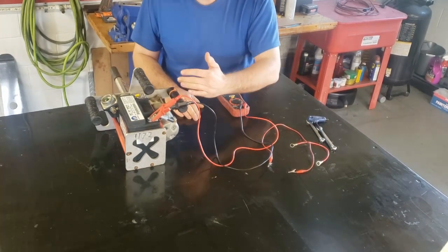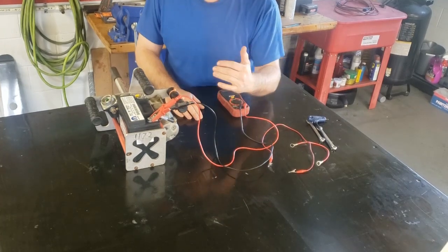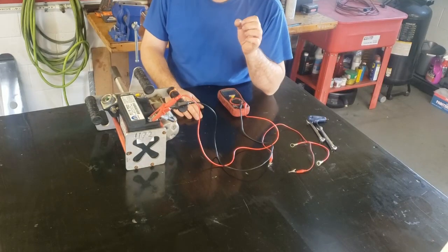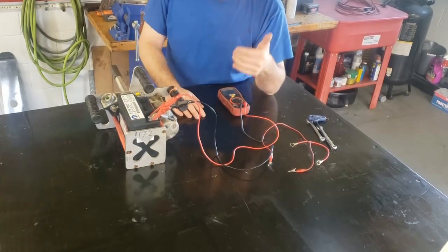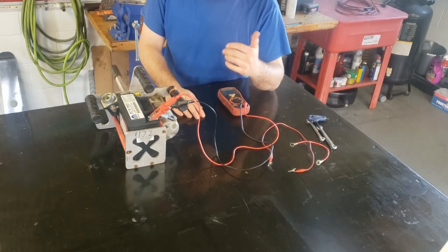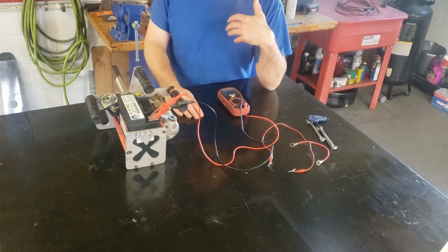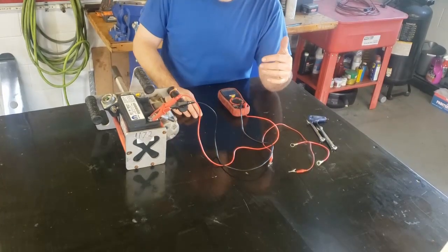The higher that number, the more voltage we are losing or dropping in that battery cable. We can use this to test any wire where we suspect a bad connection or a bad wire. It's not just starting systems. It's just the most pronounced in starting systems because starter motors draw so much current. Remember, we said that starter motors are one of the highest draw, probably the highest draw device on a vehicle.